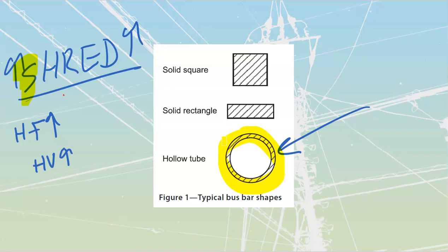You'll see them inside of high voltage installations. Sometimes they will actually run cooling components through them. They'll use them for other stuff. Other times inside of some of my high voltage installations, we will have hollow tubes, and then inside of that, supported, we will have other conductors that we can utilize. So we will have insulators that are going to hold these off on the inside, drawn in kind of like a star, although they are usually ceramic discs, and they're going to have another conductor on the inside.